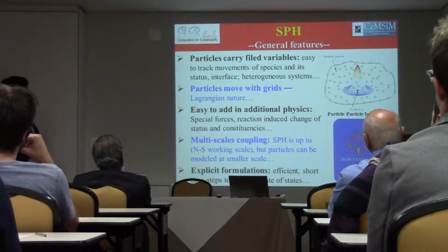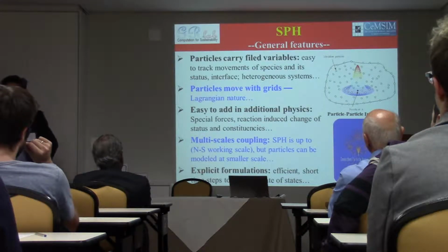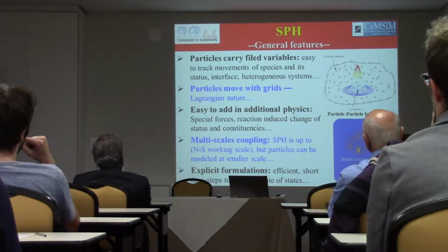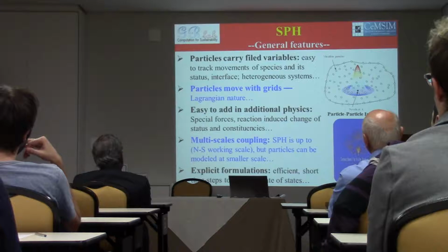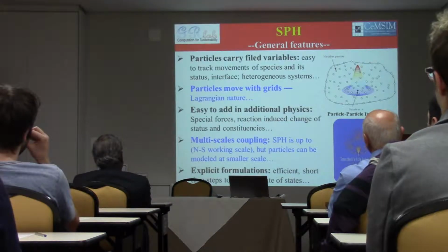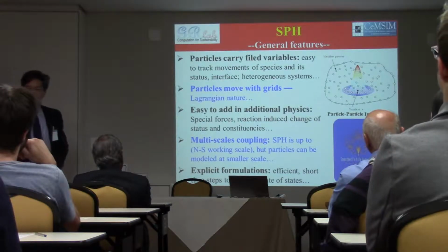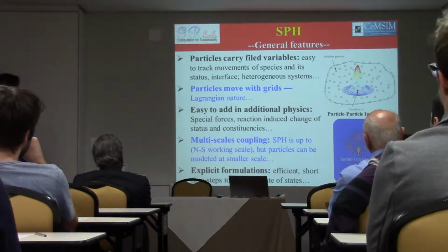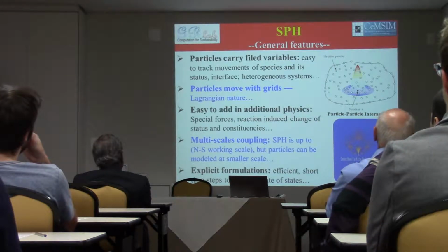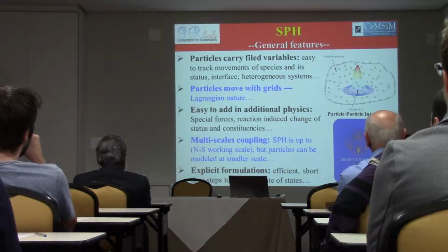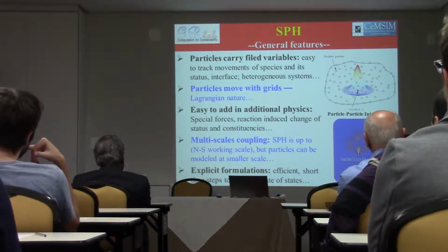The procedure of doing that is that we just discretize the domain with particles. Okay? And then we use this kind of bell shape smoothing function to perform the smoothing operation. And then we create systems always based on the Lagrangian formulation so that I can evolve this in time properly, allowing all the particles to carry the information of the field variables.